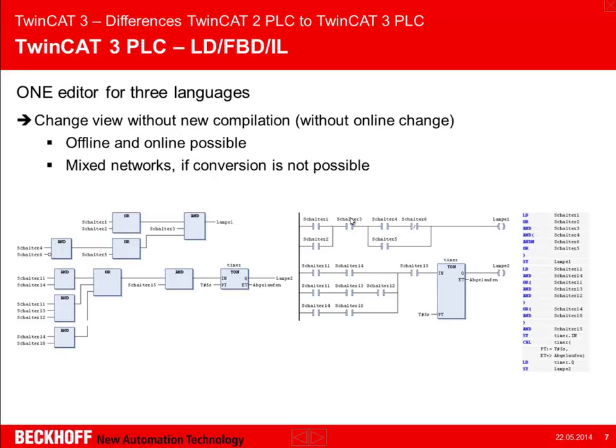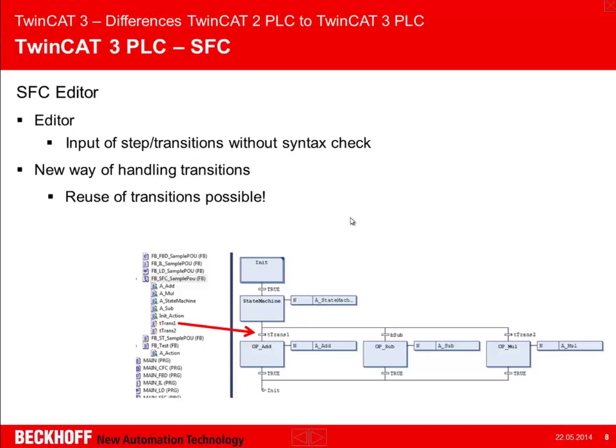Also new is the SFC editor. So first of all, it's easier to start with SFC function blocks. So you can easily start with step, step, step, and then insert the transitions. And this without a syntax check. Of course, when you do the compile or when you want to save, there is a syntax check. But from the beginning, it's easier to start with SFC.